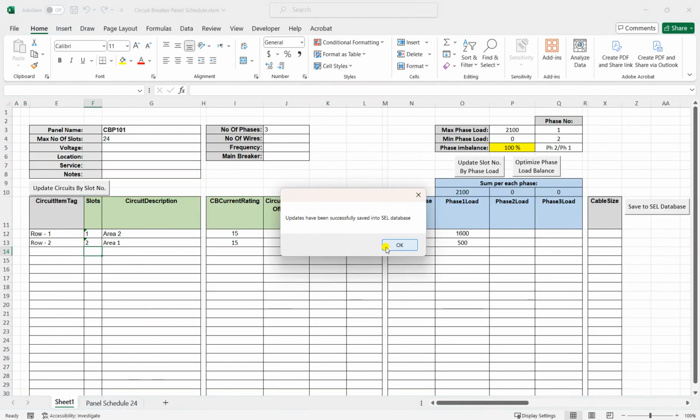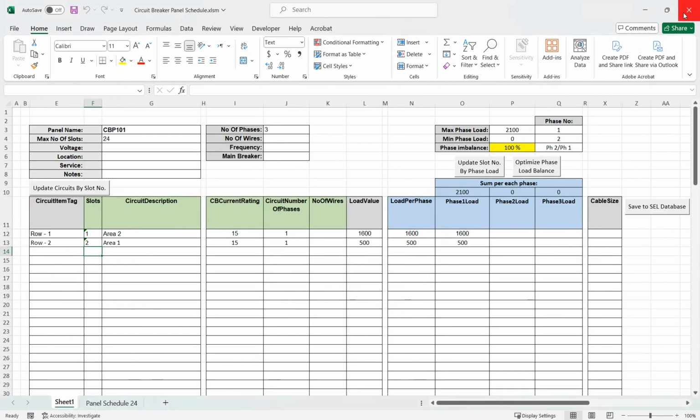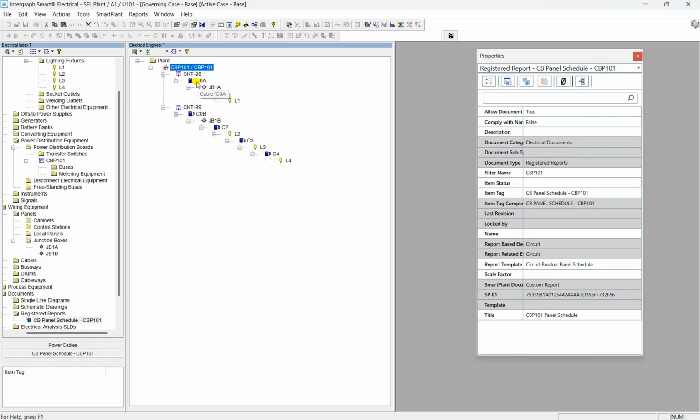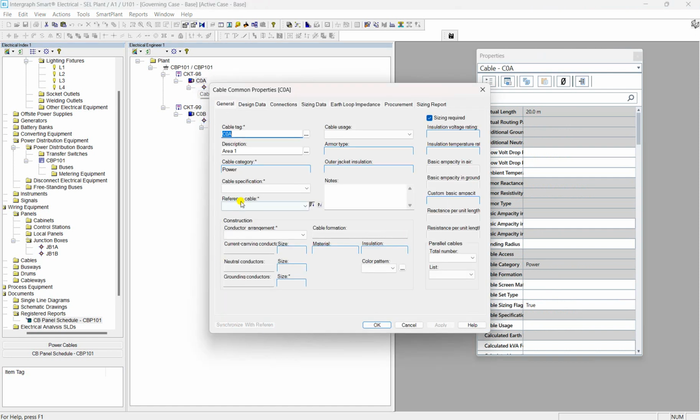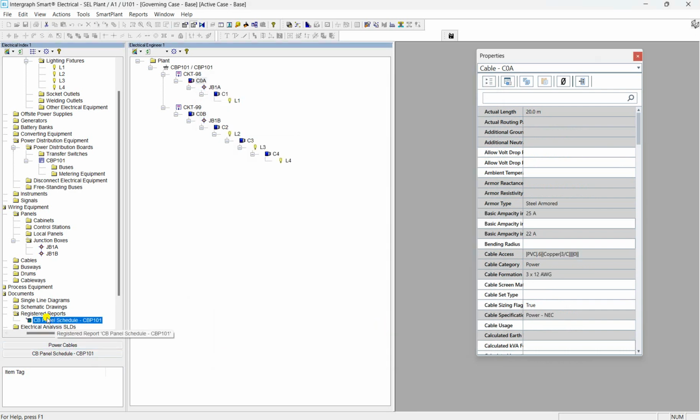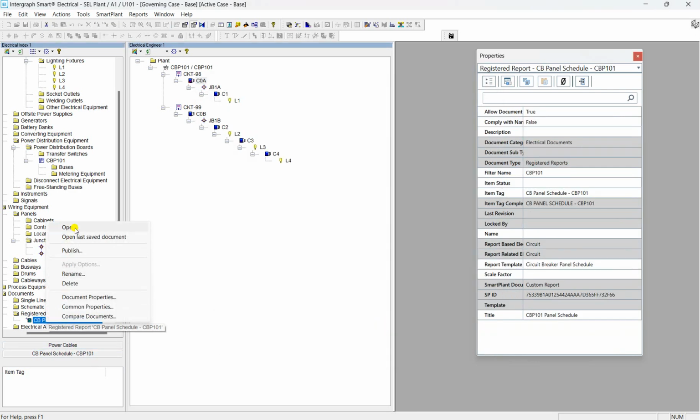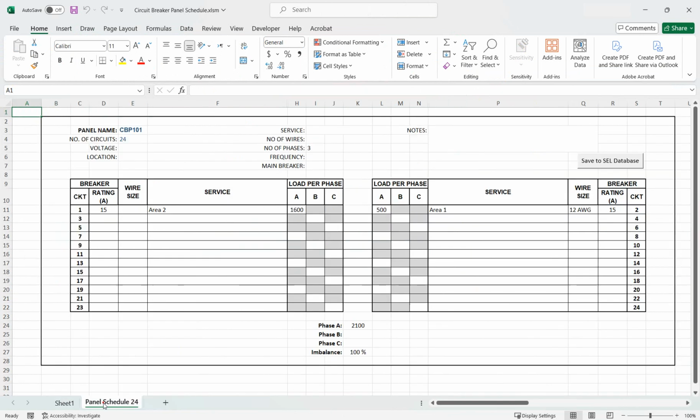The report allows identifying missing cable sizes, which users can fill in the database, and report in the panel scheduler. Please refer to my other videos to learn more about cable sizing options offered in Smart Electrical. Please note that the cable scheduler produced in Smart Electrical can be published to Smart 3D to synchronize cable sizes, verify the cables fill on raceways, and validate routing.